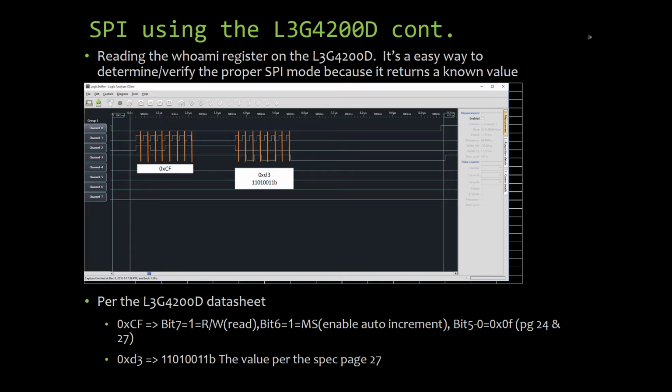But the basics of an RC radio are, for each channel, it puts out a 1 to 2 millisecond pulse at a repeating interval of 18 to 20 milliseconds. And the pulse encodes the control output. So the width of a pulse translates to a particular control request depending on the channel and the width of the pulse.